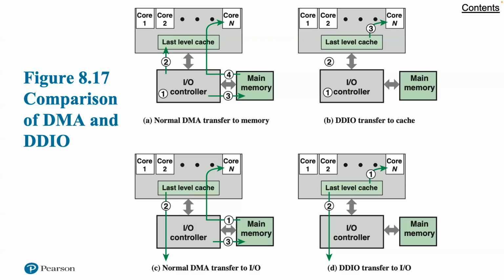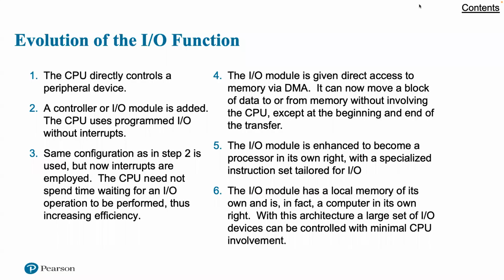The read operation initiated by the NIC is satisfied by the data from the cache without causing eviction to main memory. It should be clear from these side-by-side slides, the comparison, that DDIO is more efficient than DMA for both incoming and outgoing packets, and is therefore better to keep up with a high packet traffic rate.